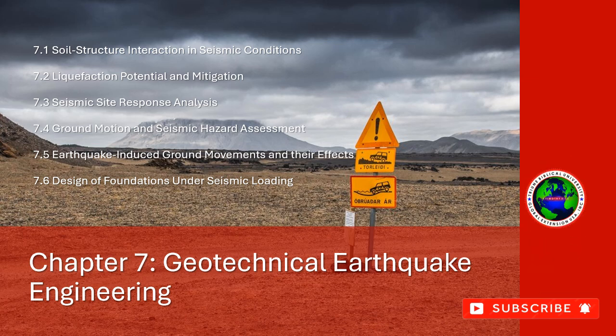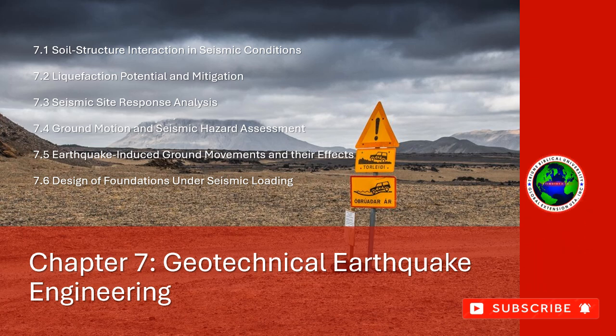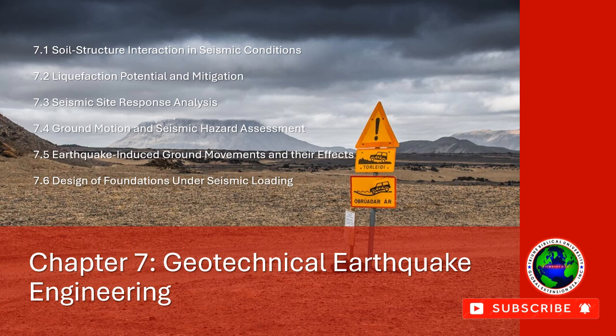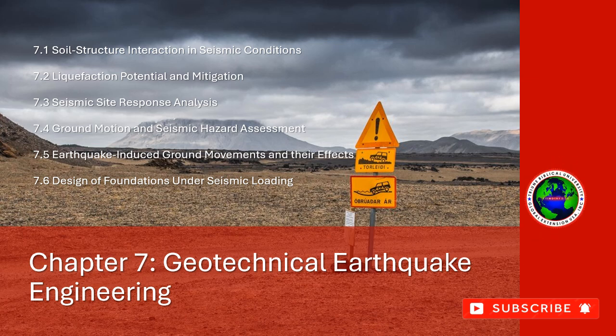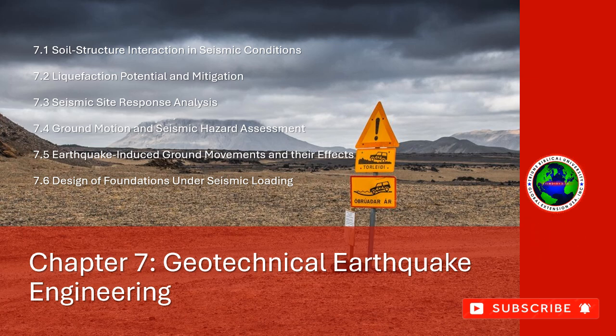Pile foundations. Piles can be used to transfer loads to deeper, more stable soil layers that are less susceptible to liquefaction. Piles are particularly effective in areas where the liquefaction-prone soil layer is shallow. Drilled shafts, or caissons, can be used to anchor structures to deep, stable strata, providing support even if the upper layers liquefy during an earthquake.